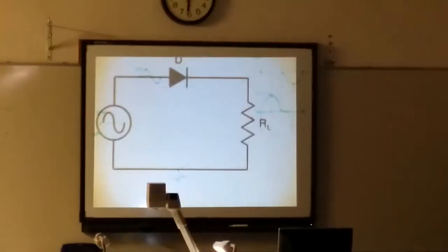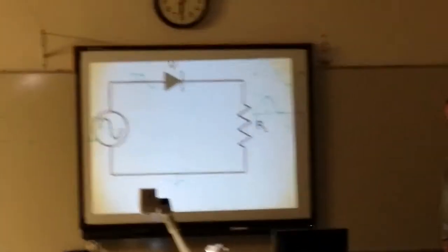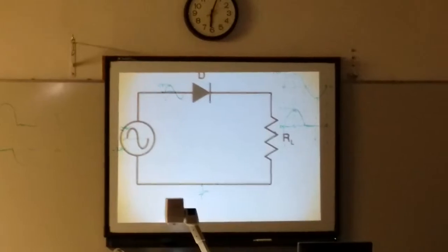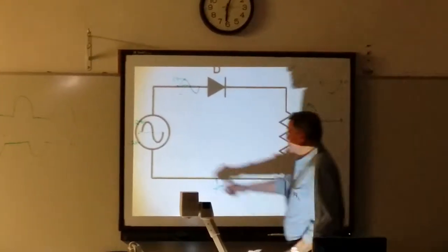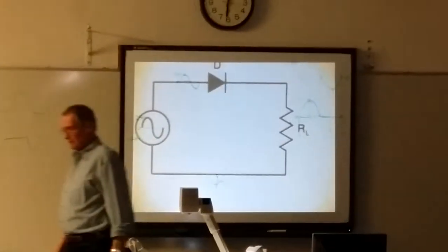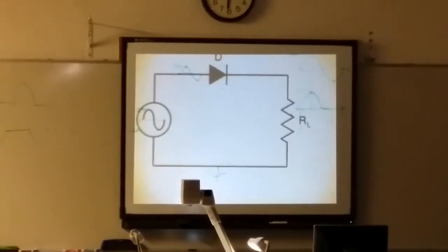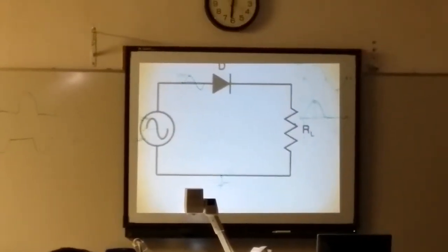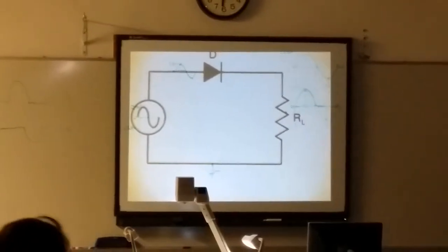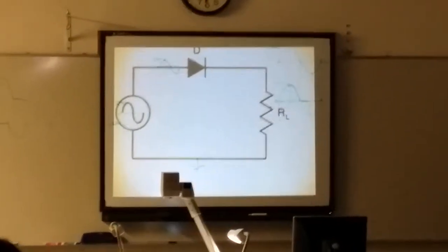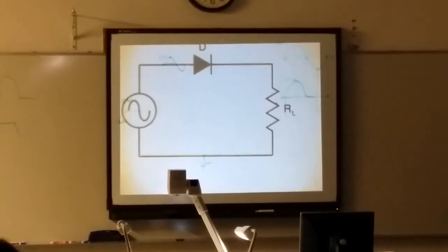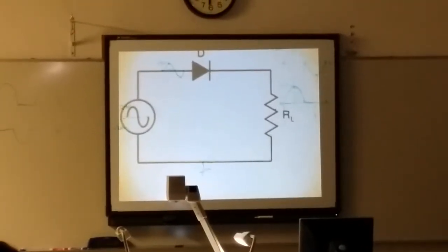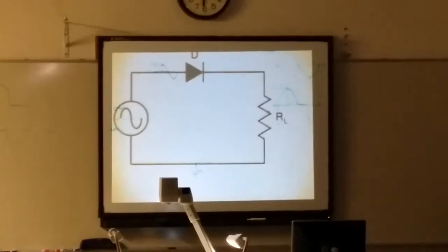Got your notes? Hey guys, flip your notes back to last week. We didn't put it in RMS. It's already in. Since it's DC, this 24 peak to peak, or 24 peak, we don't care about RMS right now. What's that say there, Jeff? DC, all DC meters read what? They read the average, right?